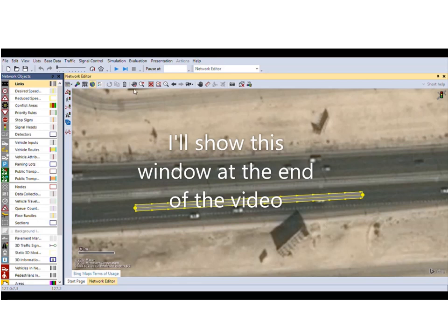and you're going to increase the number of lanes to 4, because we have 3 main lanes and 1 shoulder lane. Now, the lane indices will count from the outermost lane to the innermost lane, meaning lane index 1 is going to be our shoulder lane. So we can go ahead and block all of the vehicles from entering the shoulder lane, because that will not be part of our simulation, and you can change it to obstacle, for example. So we'll put no lane changes, and that'll have blocked our shoulder lane from being used at all.